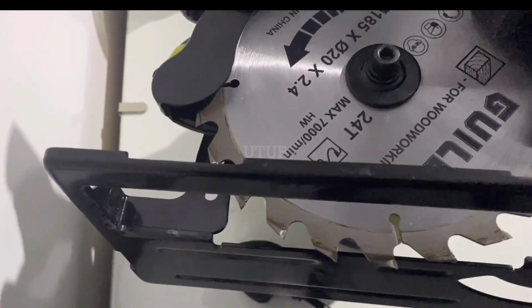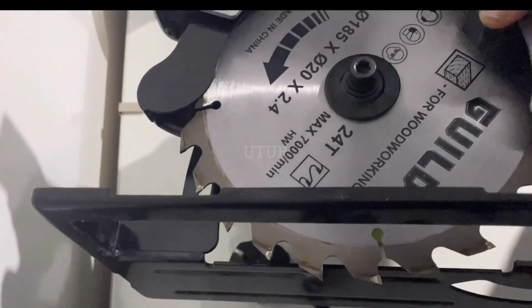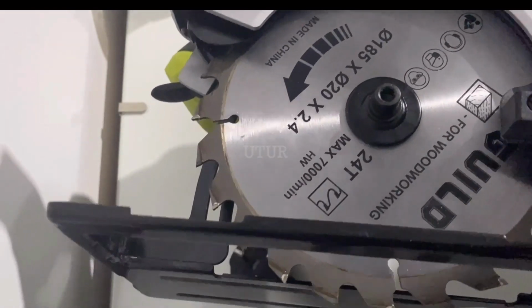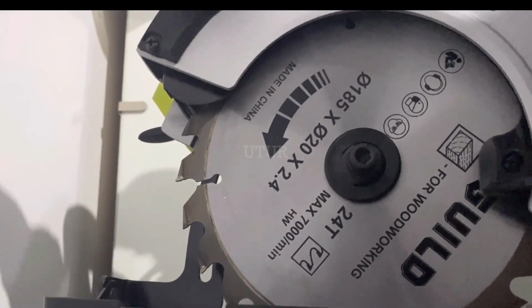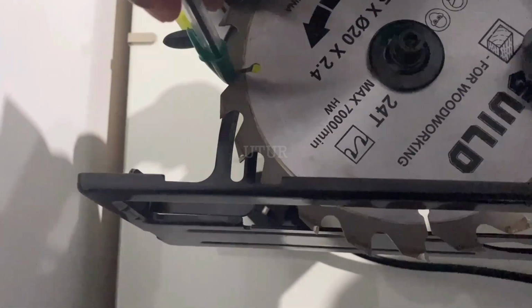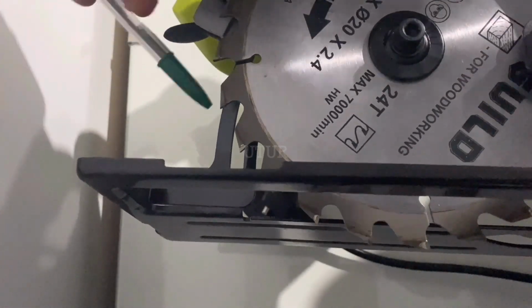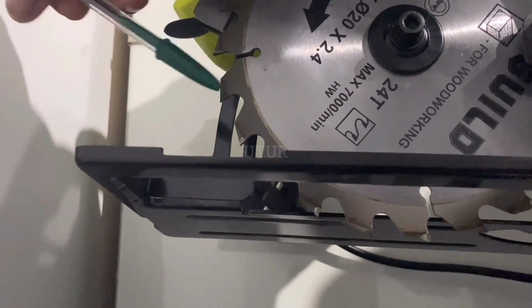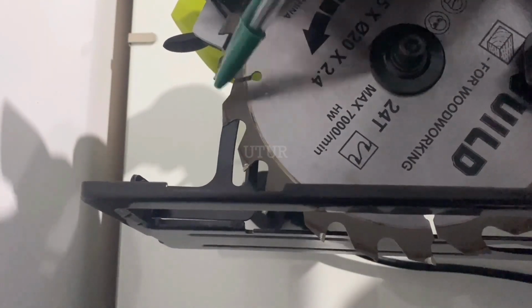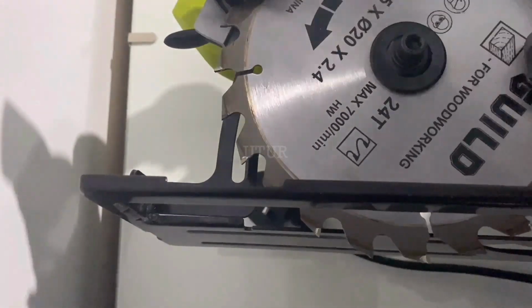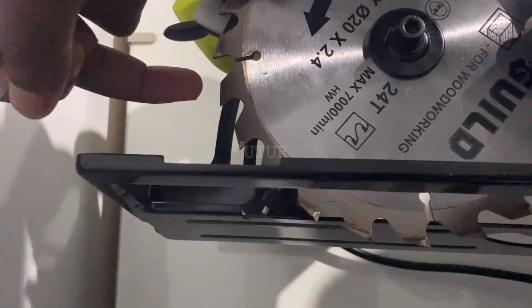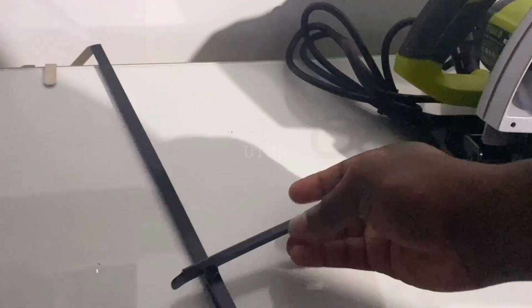So just a quick recap: when you're trying to get quality cuts, the blade selection as well as the type of material that you want to cut is very important. Here we intend to get strips off of hard plywood, and so the ripping blade with large gullets, or the open hole technology, isn't the ideal blade for getting strips off of hard plywood. You should be getting a tooth configuration that's got the ATB, which is the alternate top bevel, as well as a combination, composite or general purpose blade due to the grain structure of the hard plywood.